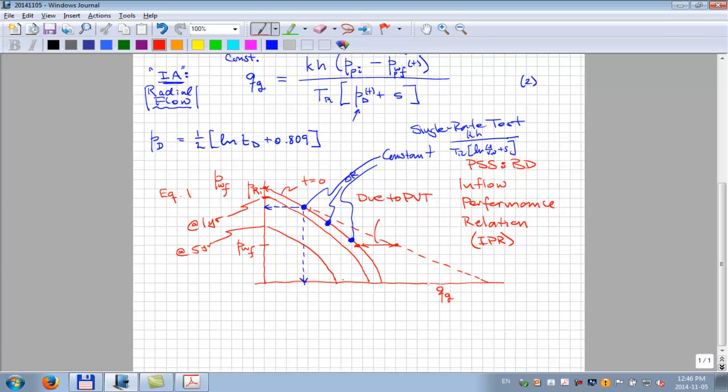Okay? And by the way, where this reaches zero bottom hole flowing pressure, which is impossible, by the way. I mean, it's not impossible. It's not usual. If you put a compressor at the top of the well, you're actually surprised that you can get a pretty low bottom hole flowing pressure. But this is a theoretical maximum drawdown, right? You can't draw down the pressure in the well any more than that, as PWF goes to zero.